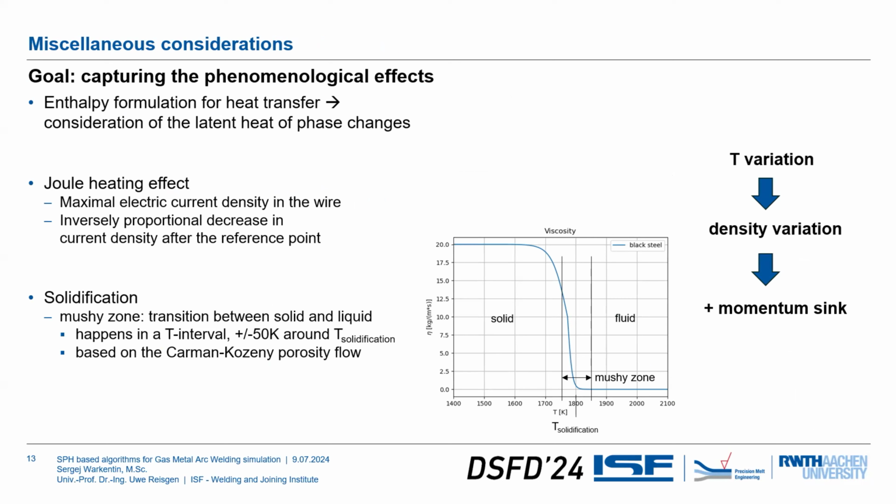As you do not include the electromagnetism of the arc explicitly, does it limit the kinds of welds that you can model, or the range of currents or voltages? That is the question of the arc attachment. Of course, it will be different, and we have to adapt or calibrate our heat input parameters.